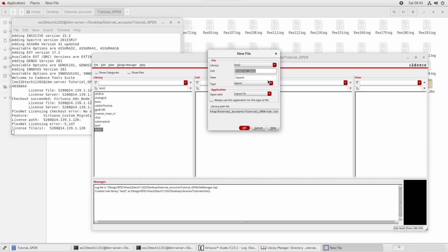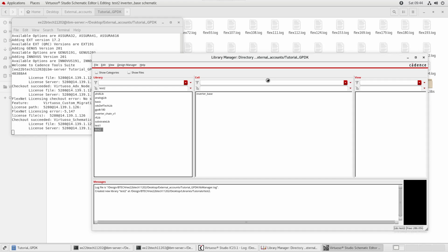And your cell name is a container rather than a single design. Because you can have multiple schematics for a single cell, you can have schematic, you can have schematic v2, you can have schematic backup. So all of them being independent. They won't be completely independent because of things like symbol, but as far as simulations are concerned, they are pretty independent.